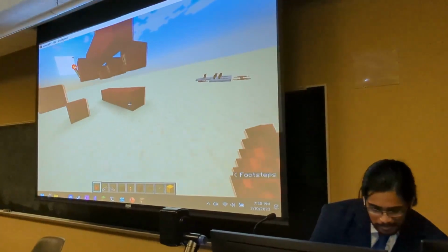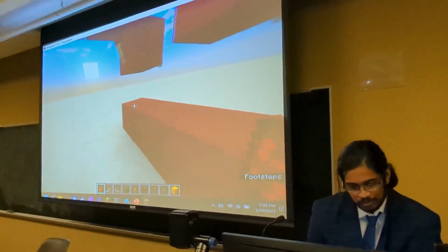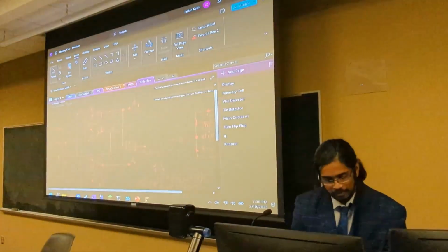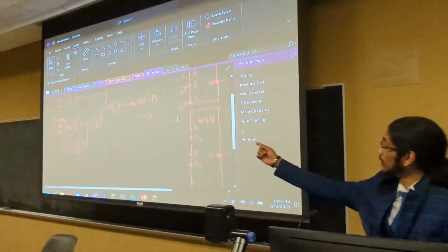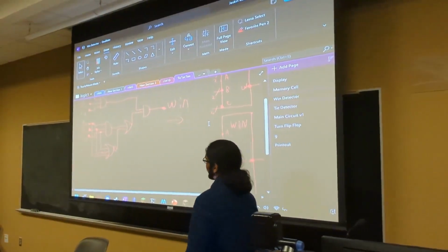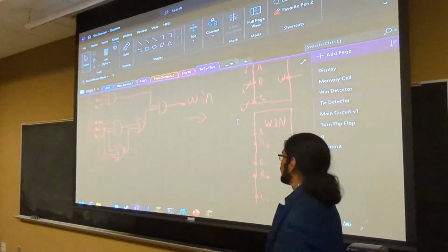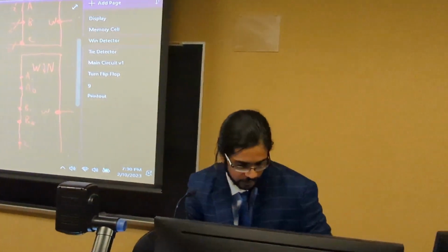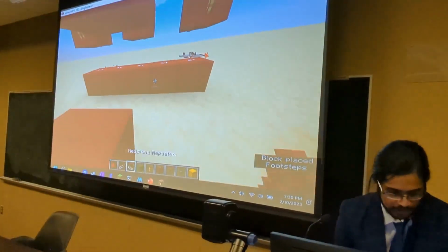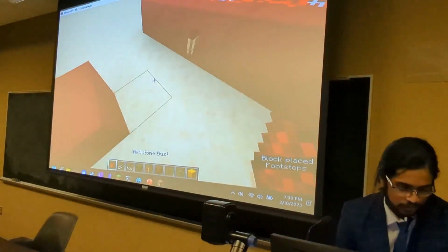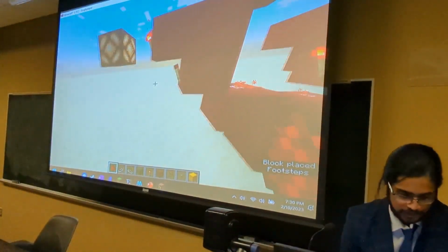And then all we have to do for that last part is, if we go back to the win detector, we need an AND gate here for detecting if they're occupied, an AND gate here for detecting they're all X's, and then we finally need that NOR gate down there. So an OR gate is just connecting lines together. A NOR gate is you just invert that, right? So we can take that and also feed it in.